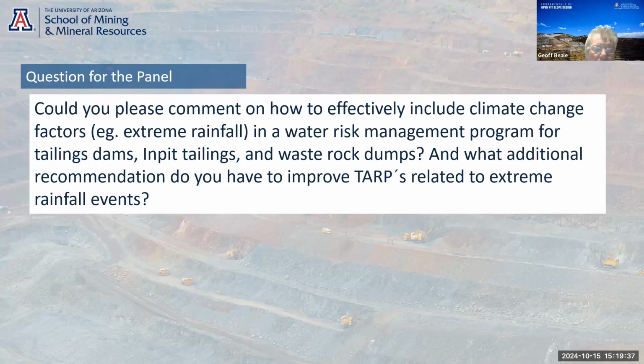That's less of an issue for in-pit tailings. It depends. If it's purely an in-pit tailings, there's typically very few geotechnical concerns. There's potentially no credible failure mechanisms for some in-pit tailings, so the stability is less of a concern.